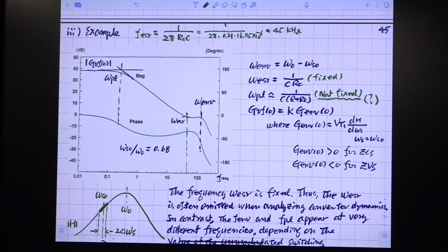Okay? And the switching frequency of this setup. In the simulation, the resonant frequency was 414 kilohertz. And the switching frequency was the ratio between this, as shown here. He specified all these details in his presentation. And Fs, then Fs is 280 kilohertz.